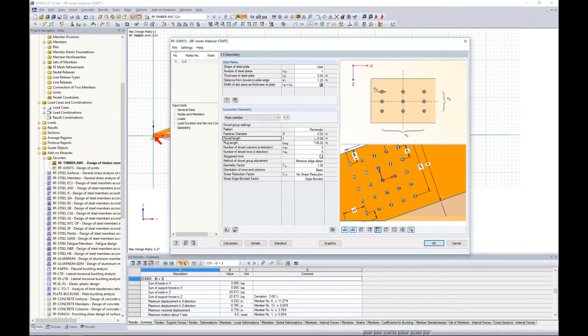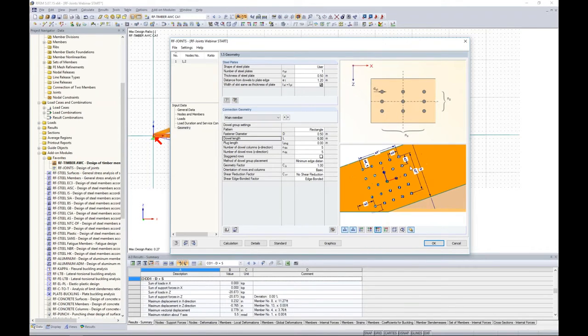Now the dowel length is automatically calculated simply based on the thickness of my member, my glulam member. So this is set at 6 inches for the thickness of the member. Now perhaps I would like to not see the dowel holes, for example, and I want to put a plug on either side of these. Well, here's where you can set that plug length of maybe 0.5 inches. And you'll notice that the dowel length automatically takes that into consideration and reduces to 5 inches. For today, we will leave the plug length as 0.